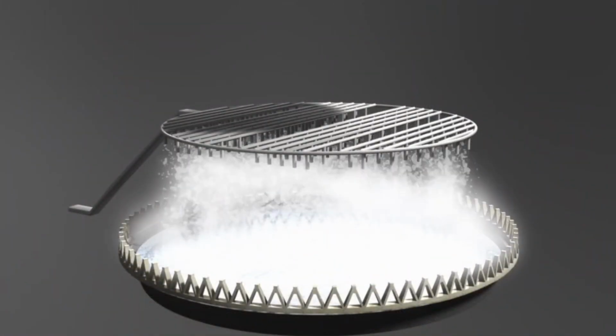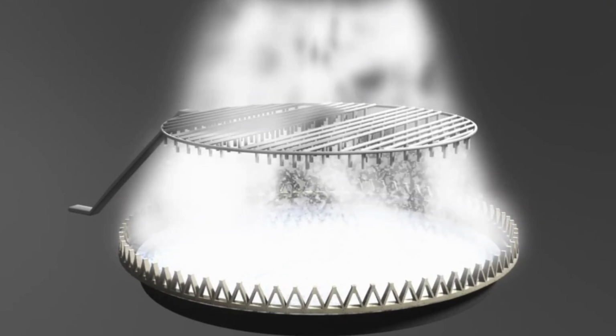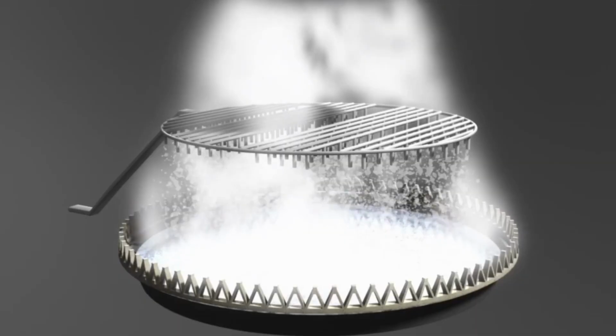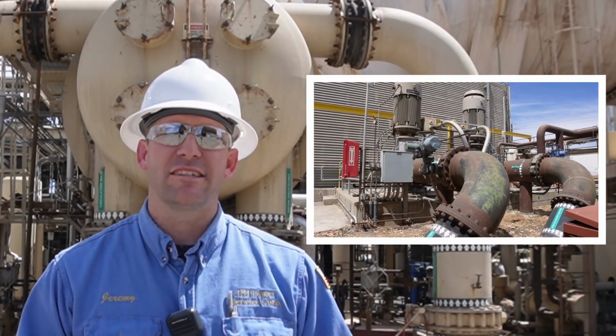Now, regardless of the design, the objective is still the same. Maximize the surface area of the water so that the upward moving air can extract as much heat as possible, allowing the water to be recirculated through the system. After the water accumulates at the basin of the cooling tower, it will then be picked up by one of two pumps. These pumps send water to two separate and distinct systems.